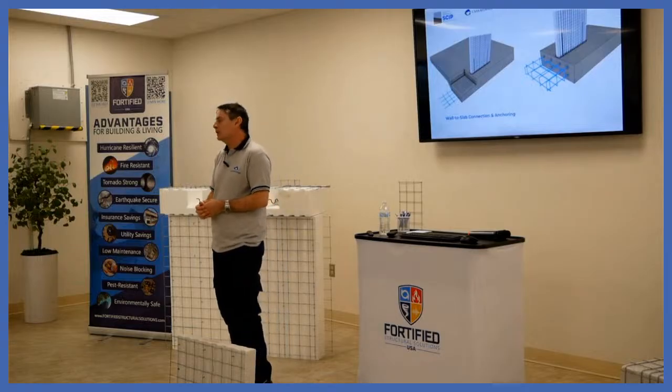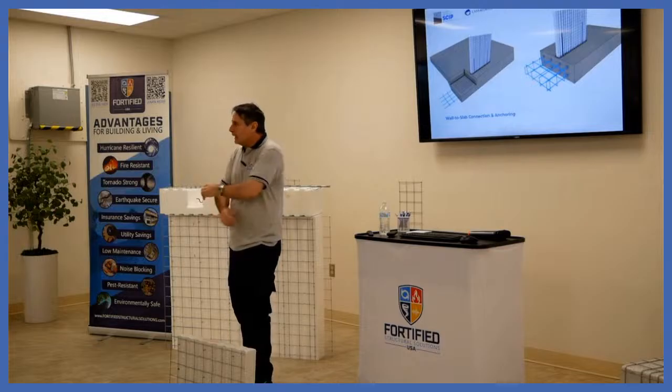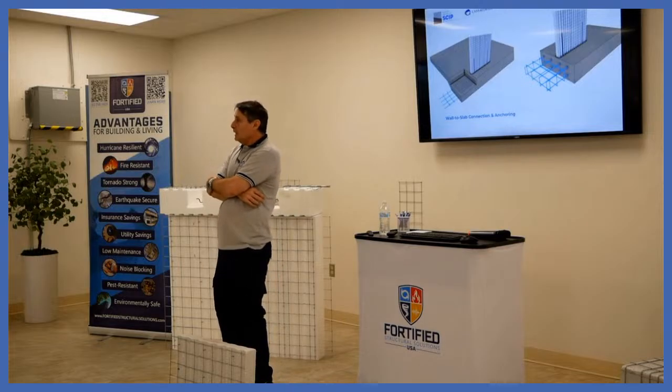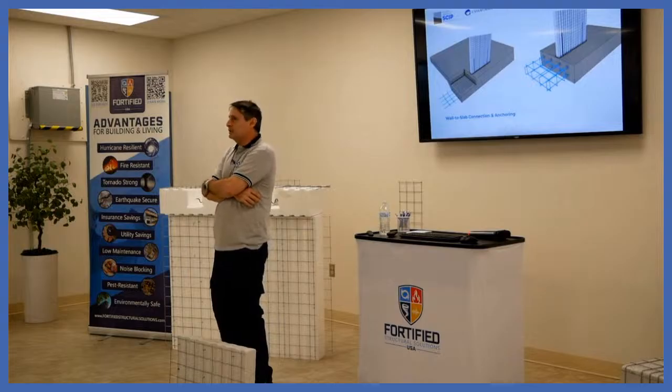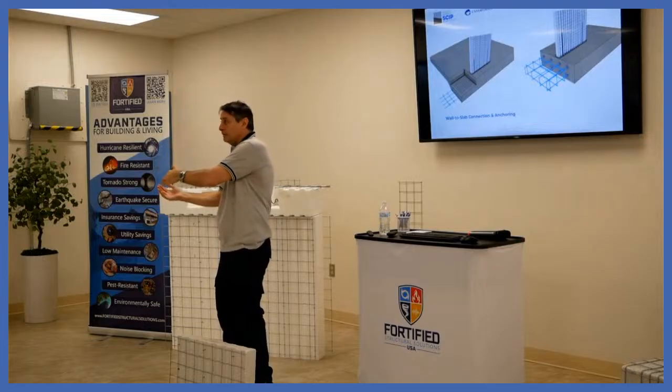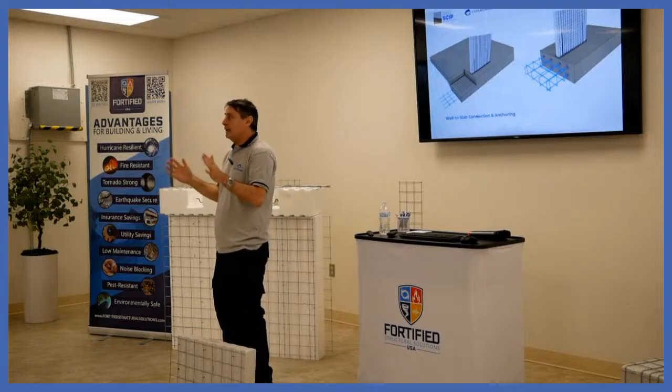You spray the outside first, then you spray the inside, ceiling, shore everything, and then you're pouring. But the thing is that you already placed the floor panel. You already connected them, everything tied together. So everything has to be tied together, as you have here on your model outside.